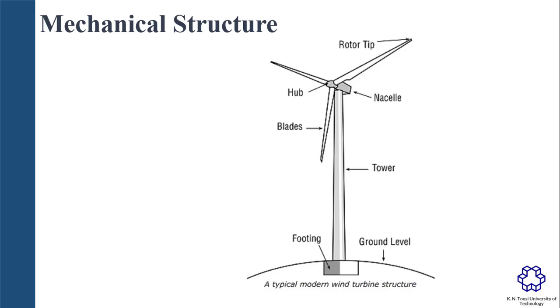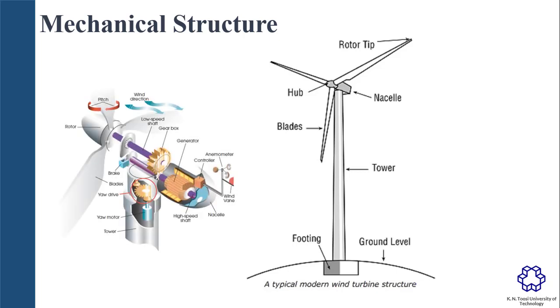There is a lot going on in the nacelle, but for the sake of time I will mention the most important components. As I said before, the blade mounted on the hub rotates the low-speed shaft. This shaft then connects to a gearbox, which rotates a high-speed shaft connected to the generator. There is a brake system in the nacelle to stop or hold the rotor. The pitch angle control system is in the nacelle as well, but the yaw angle controller is inside the tower. However, in Simscape, I will consider the yaw angle controller inside the nacelle too.